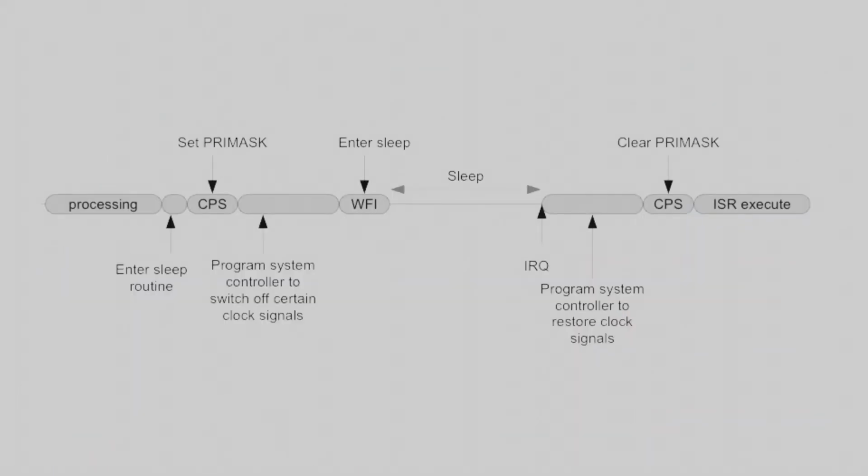I can already hear some of you scream, but there's also WFE. What about that? In my opinion, WFE wakes up the core too much. WFI gives an exact moment of when the core will wake up.